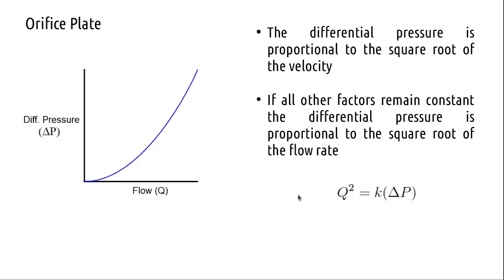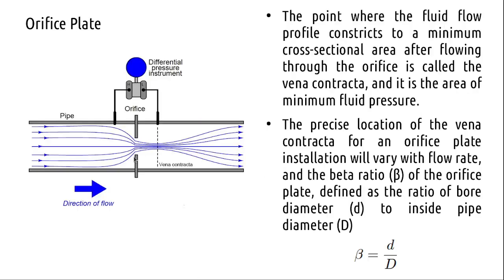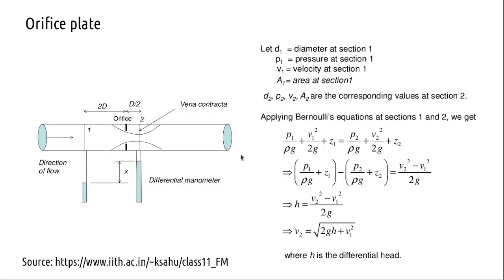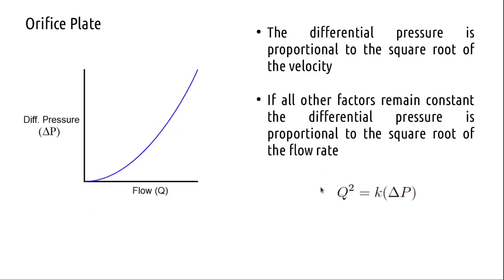So what we are going to measure is based on the differential pressure, P1 and P2, as we saw here. This is a simplified statement of your Bernoulli's equation. Applying the equation of continuity along with Bernoulli's principle, you end up with this expression.